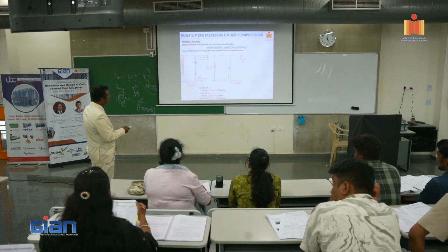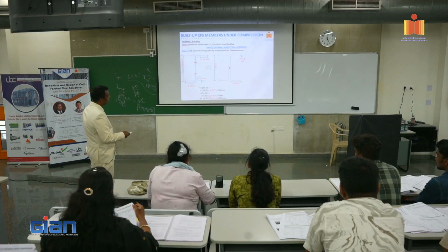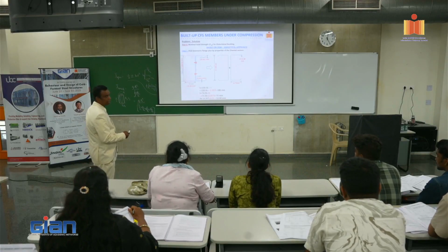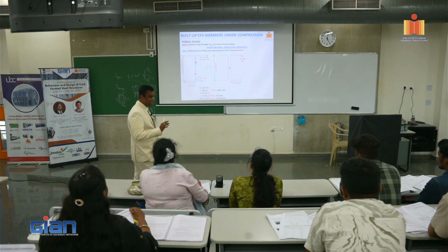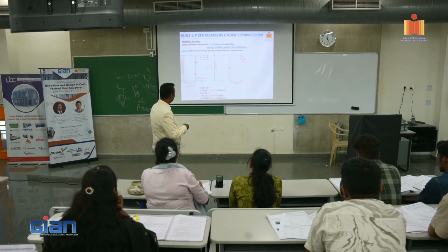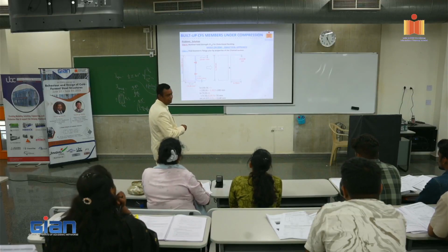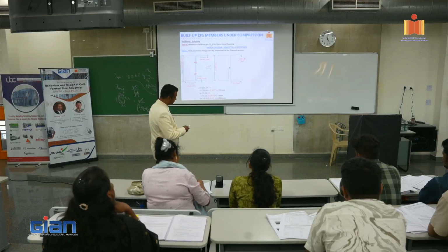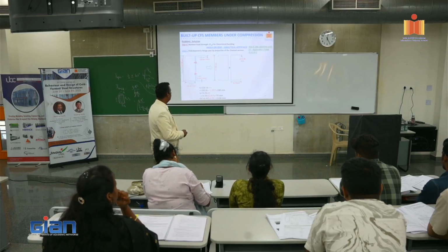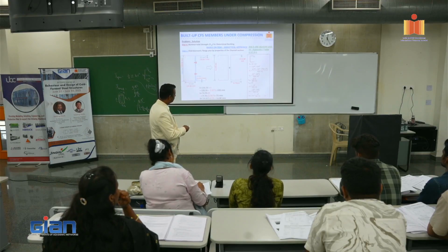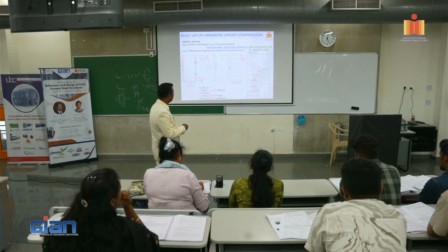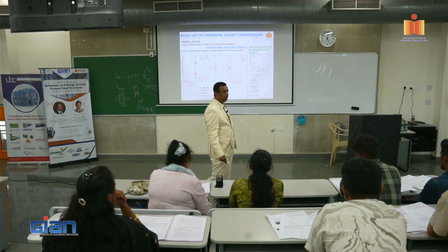Because the codal provision gives you some formulas to calculate that based on the centerline stiffness, centerline method. Right? So now you have 2 back-to-back centerline channel sections. So what do I do here? I go to the appendix table 2. It's very simple. AF, JF, IXD, IXF, everything you can calculate using the centerline method, right? You have done that.